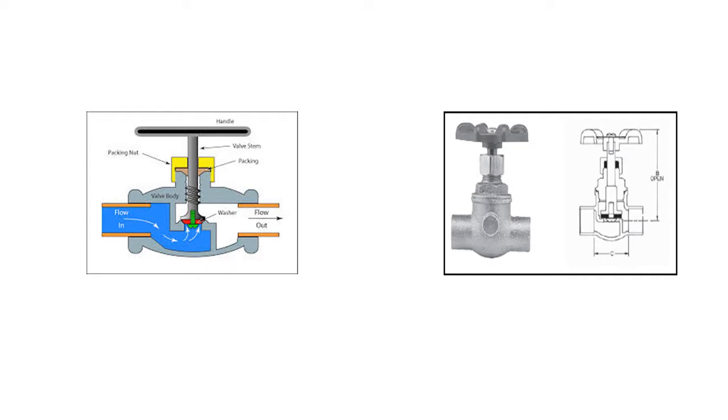The valve shown here is a globe valve. These valves are used for regulating flow in a piping system. Globe valves have an arrow imprinted on the body telling which way the direction of flow should be for the valve to operate properly. Globe valves are named for their spherical body shape, with the two halves of the body being separated by an internal baffle.